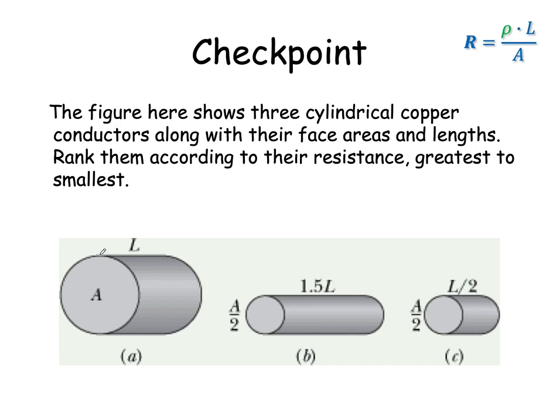So here's a quick conceptual question using the idea of resistivity. Which one of these would have the greatest resistance? Which one would have the least resistance? Hopefully you would recognize, all right, the longer they are, the greater the resistance, and the smaller the cross-sectional area, the greater the resistance. Which one has the most resistance? You should say, oh yeah, this one here. So B has the most resistance, followed by, trick question, this one has half the length and half the area, then this one is greater than A equals C. Both of those have the same resistance, and they're the least.